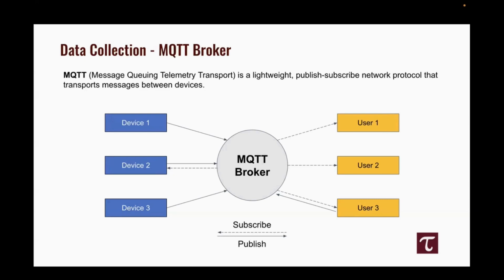Now think about this. If you have sensors on your farm, how will you use it? You need to set up some client side. You need some computer on your client side. That's why I'm talking about edge computing. On that side, all the sensors can send data to different connected devices. The device can run a simple MQTT client. The broker is a server I'm running, sitting there somewhere. The client side can get the data and send it to this broker, and the broker will figure out how to send it out to others.